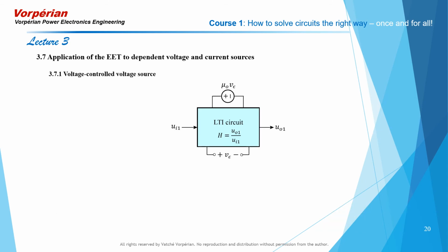And now we try our second choice for mu 0. We let mu 0 go to 0. And in this case, the form of the extra element theorem is as shown here. First, you compute H0, which is the transfer function with mu 0 set equal to 0, followed by this correction factor in which we have computed the null inverse gain and the ordinary inverse gain.